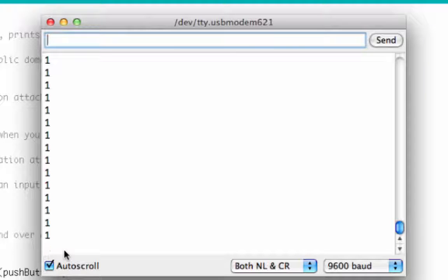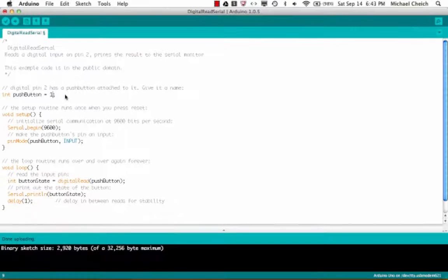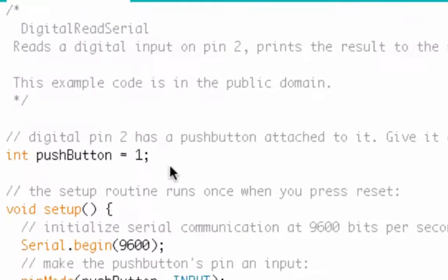And when you try to dual purpose that pin and transmit a bunch of information at the same time, there's a very high potential that you're going to run into troubles, like this weird stuff that's going on. So the takeaway from this is, if you're going to be doing a lot of transmitting and collecting information on pin 1, you might consider changing the pin number. If you have another pin open, instead of using pin 1 to collect information from, say, a button like us, use another pin. Okay, so now let's go ahead and try pin 0.